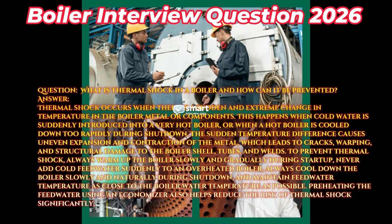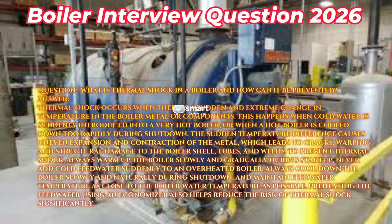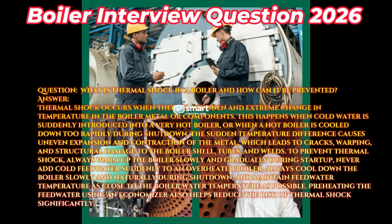To prevent thermal shock, always warm up the boiler slowly and gradually during startup. Never add cold feedwater suddenly to an overheated boiler. Always cool down the boiler slowly and naturally during shutdown, and maintain feedwater temperature as close to the boiler water temperature as possible. Preheating the feedwater using an economizer also helps reduce the risk of thermal shock significantly.